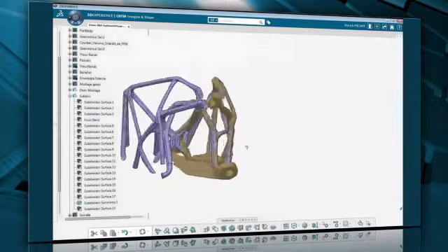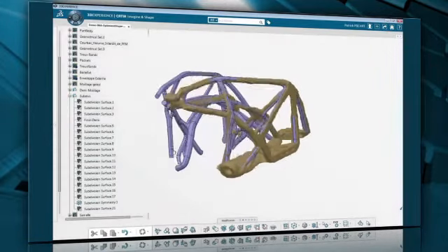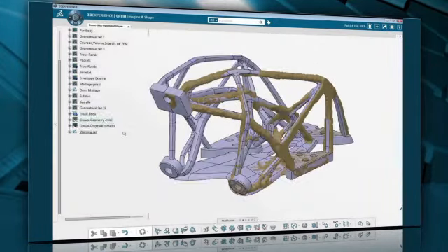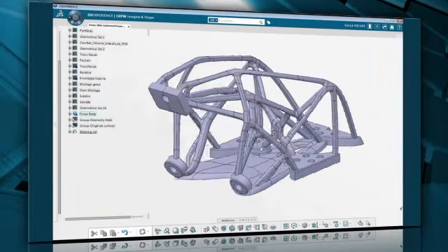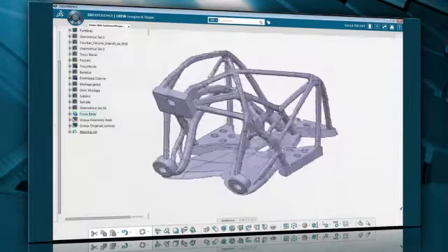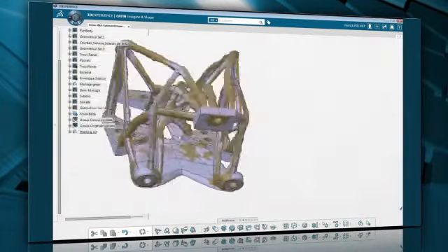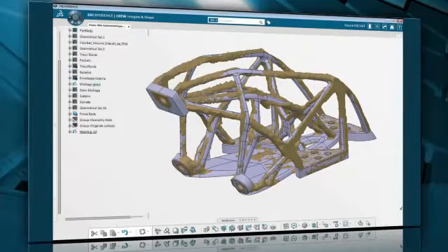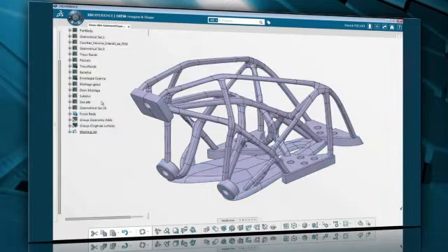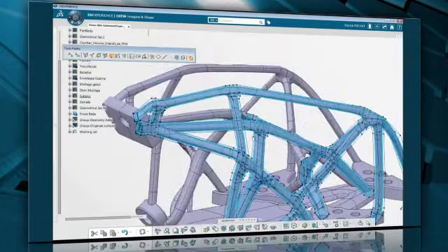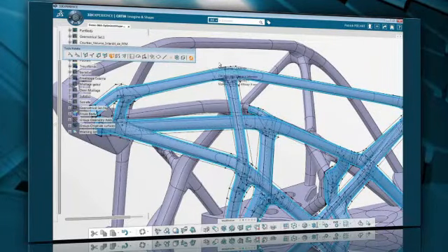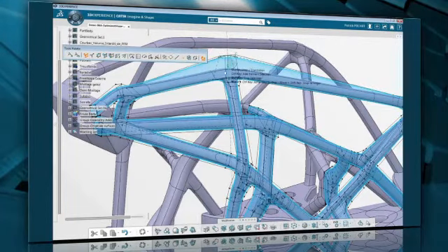Then, Imagine and Shape allows you to mirror the other half of the symmetric part. The base plate of the part can be created using the classic mechanical CATIA tools or also by Imagine and Shape. In this case, it's been created with a mix of both technologies. First, the shape was created using Imagine and Shape, and then it's completed with the standard part design tools, mainly trimming and filleting. Another very powerful feature is the fact that this is still very easy to modify based on validation and finite element analysis recommendations.